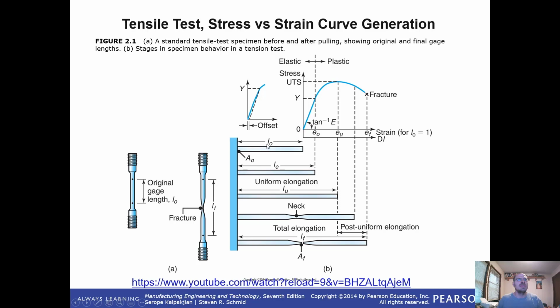It's showing L0, and you'll get used to these notations, especially if you do a lot of engineering work or go further on the math side of engineering. We'll be doing quite a bit in our courses, but if you go to a 4-year degree, you definitely use these. These are called subscripts. Here it's saying length 0 is the initial length. Our LE here is uniform elongation, so up to a certain point in our stretching, we'll have uniform elongation.